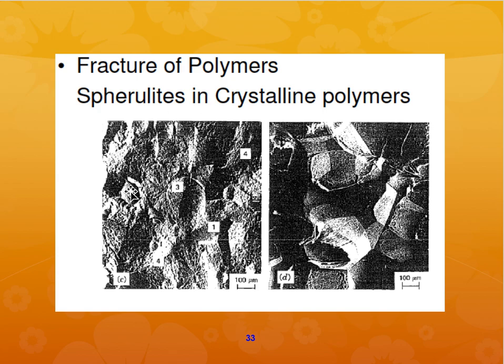So what are spherulites? Spherulites are areas where there are spherical particles, and that could be a weak point for the material when it is being tested in tension or in 3-point bending. Those could become areas where there is extra stress concentration. When that happens, the material will tend to fail at a much lower load than its original fracture strength.